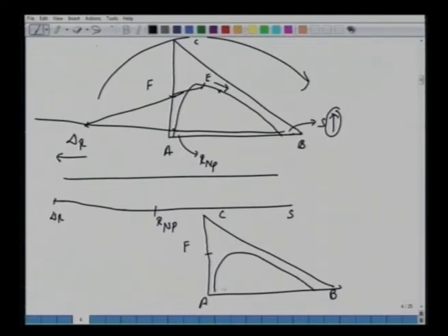So it's very important that we understand the locus of this del R points here. At a certain amount of solvent, if del R is on the left hand side, like in this case here, we increase the amount of solvent till this line becomes parallel to this. It keeps on moving in this direction till it becomes parallel to this. We further increase, now the line appears on this right hand side. So we have now this F and A. Now let's see what are the conditions when the operating line becomes parallel to the equilibrium curve.